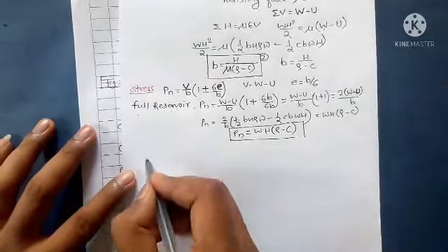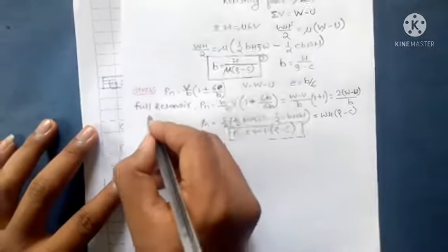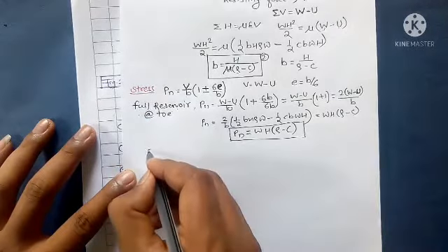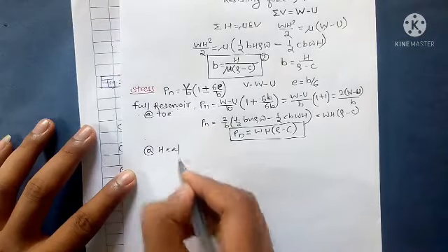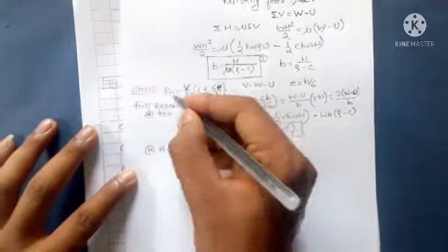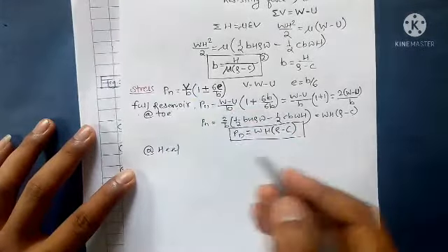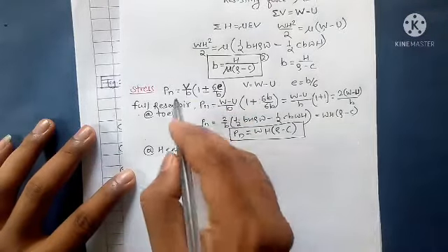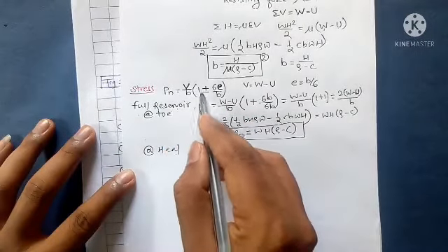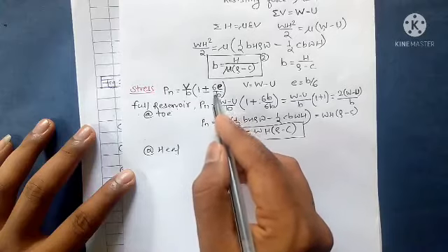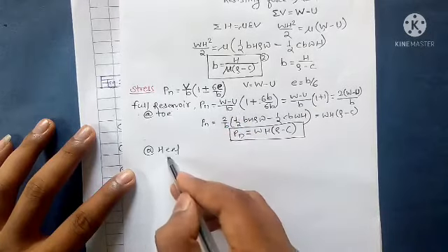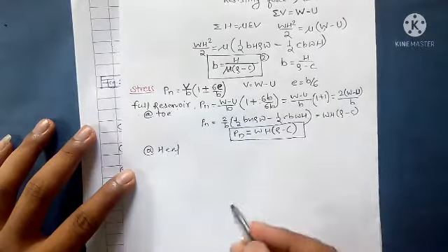Also the corresponding stress at the heel. We have Pn is equal to V upon B into bracket 1 minus 6e upon B, because for the heel we take negative.